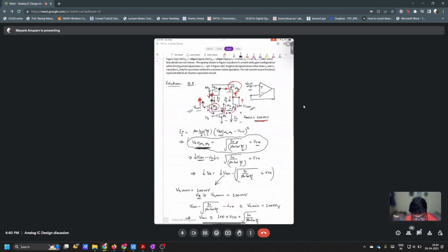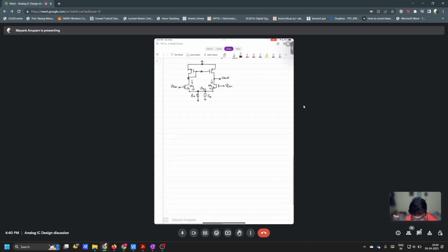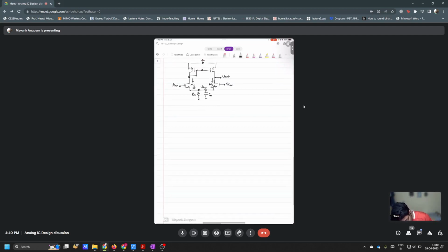In the video, what they did was connect a Vterm, a voltage source, to the Vout of the differential pair with an active, current mirror load. So this is the circuit, right? Yes, sir. It was in the differential mode, not the common mode. Was the circuit fully differential, or was it a current mirror load? Current mirror load. Okay, so current mirror load here, and there was a current source here. Now they have connected a source whose value is Vterm to this Vout, and they have connected a voltage source here.